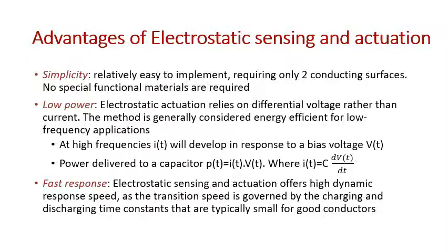But there are also certain disadvantages associated with electrostatic sensing and actuation. One such disadvantage is the high voltage that is required for actuating operation. High voltage is also going to introduce electronic complexity issues and material compatibility issues.